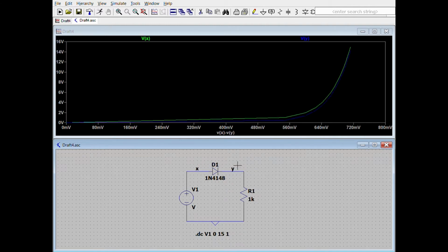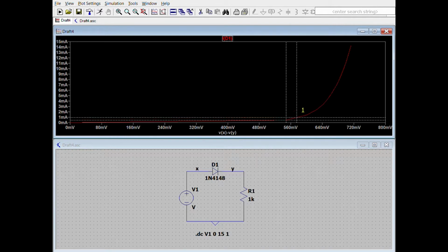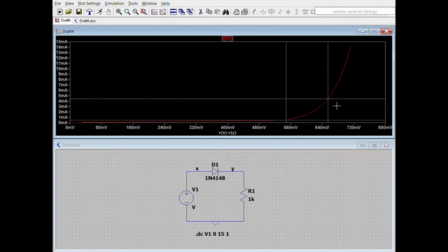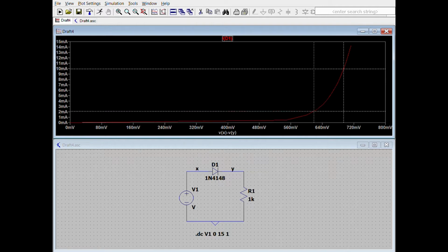So here is the graph for the diode model circuit. And to find Rf, which is the dynamic voltage VD over the dynamic current, we can just click on 2 points on the graph and calculate using the given formula in the lab sheet. So that's for circuit 1.